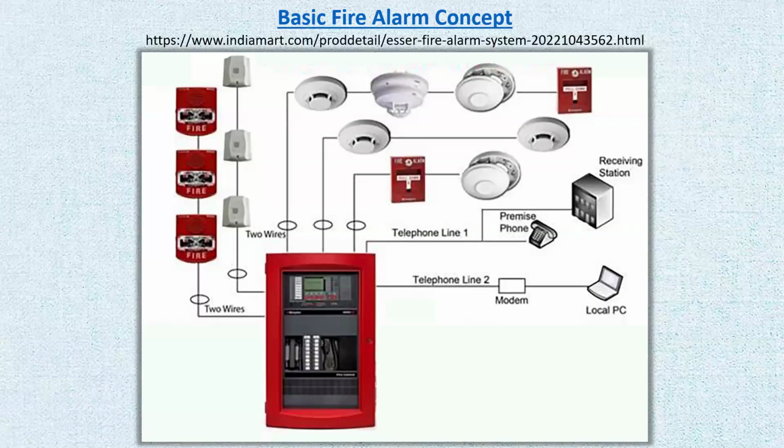So depending on the situation, the fire extinguishers should be chosen of the proper type, proper size, and proper placement has to be also satisfied. So as far as the fire extinguishers, there are also, as I say, rules and regulations on how many times a year they should be inspected by the client, and there is going to be a certain type of label or sticker, like a piece of paper there with a place to write a date and the signature of the person who has inspected that monthly.